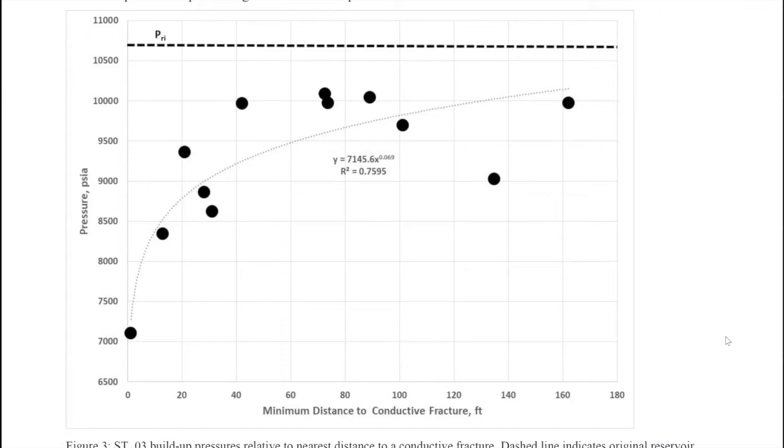Now, it's possible that there are planes of weakness and natural fractures that are contributing to the system permeability. So when I talk about the matrix perm, generally what we mean in a ResFrac simulation by matrix perm is the system perm, the aggregated perm of everything together in that block of rock. And maybe the natural fractures and planes of weakness contribute to that.